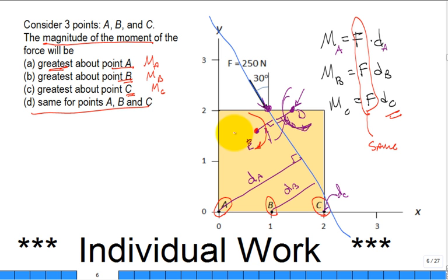Counterclockwise. It's the counterclockwise. So this is our positive sense, and this is our negative sense. One thing that this equation doesn't give us, which the cross product will give us, is the plus or minus direction, the sign. For this one, you always have to use your right-hand rule and determine that sign, so that you could say, oh, it's going to be rotating in the positive counterclockwise direction or the negative clockwise direction. Okay? All right.